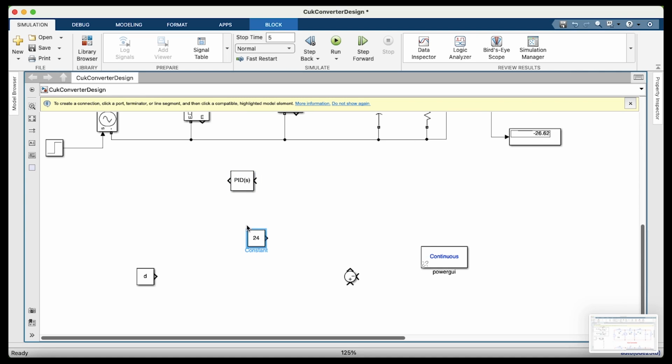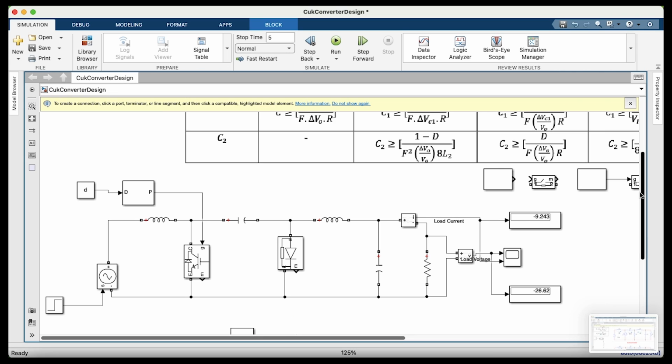So we will take a constant voltage equal to 24 volt. I am going to reverse the polarity because I am getting a negative value, so I slightly change the connections. I connect the ammeter with negative to the capacitance C2 side, and positive terminal to the voltage side.